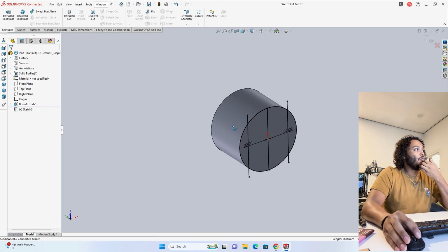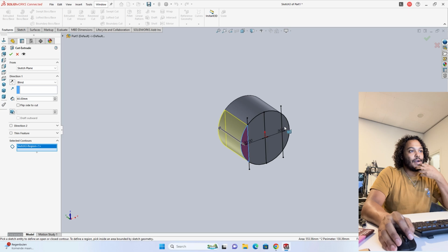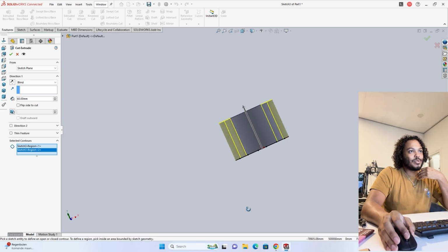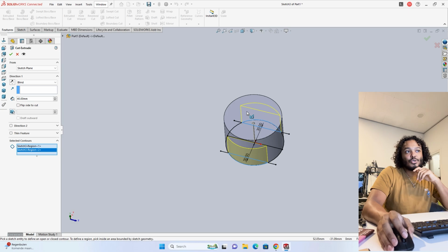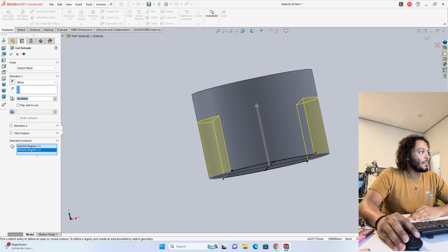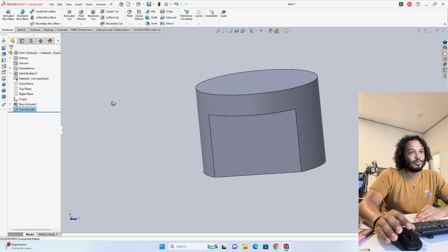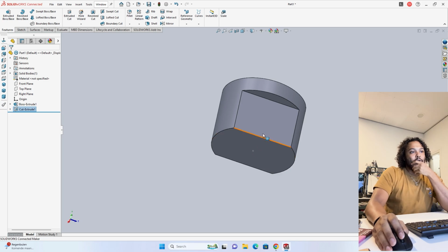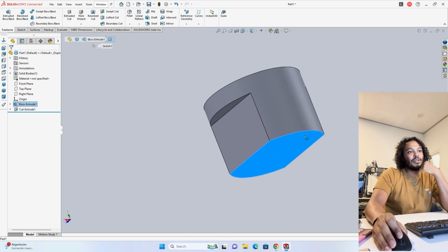And then once again, now that we have this sketch, I pressed extrude cut, and I can cut off these end caps. I don't need to do that all the way through because we still need to maintain a solid piston surface that doesn't allow gases to just flow into the engine block. But we also need it to be maybe like this, 45 millimeters, something in that region.